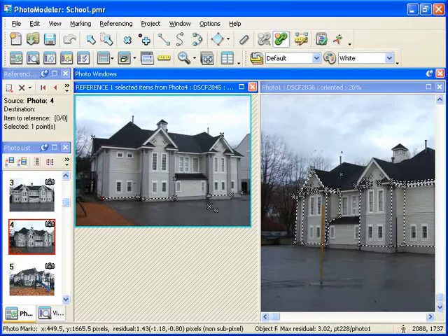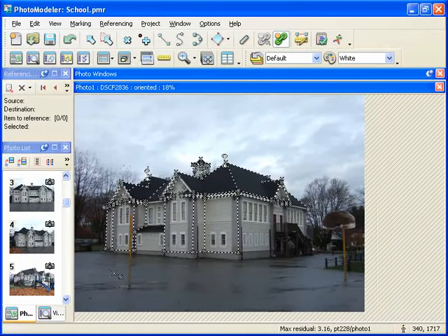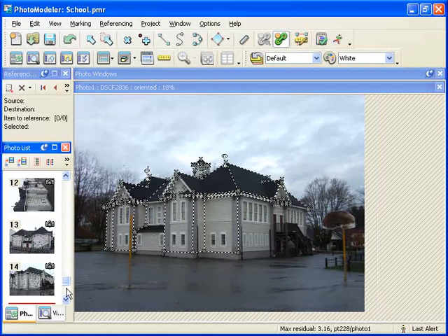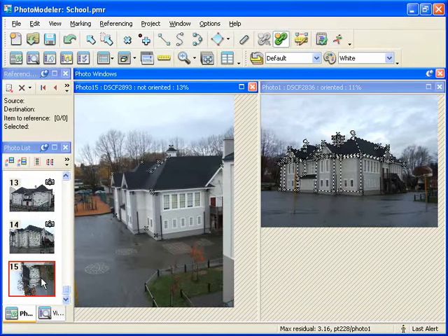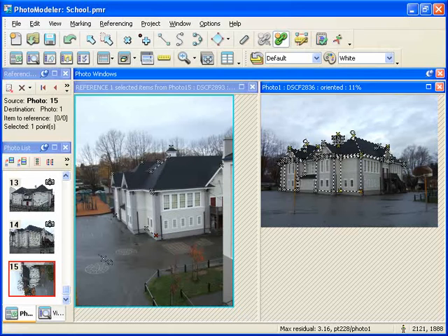When automatic processing is turned off, no new orientation changes or global optimization will be performed unless you manually run processing using the Processing button. For example, here is an unoriented photo with sufficient marks referenced that orientation can be done. If we reference these points, the photo remains unoriented and processing is not run. We are able to do these actions without automatic processing running and causing a delay.